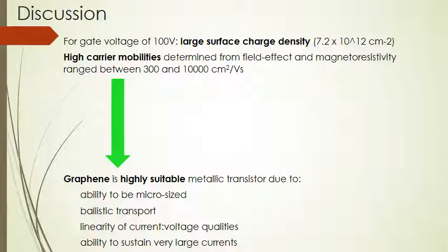The limited on-off resistance ratio of the material is a limiting factor, but that's a limiting factor of any material without a band gap greater than Kb times T. But it can be increased by using P to N junctions or local gates and even point contact methods.